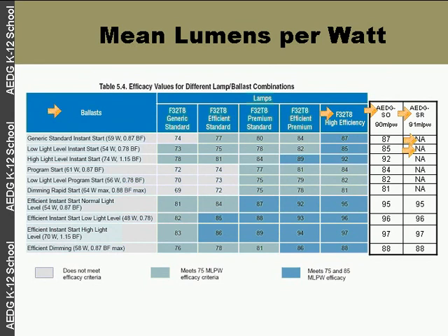We are seeing a requirement of somewhere between 5 to 7% of the floor area in skylights. So if you've got a 50,000 square foot warehouse building, you need 5% of that or 7% of that, somewhere in that range, in skylights in the ceiling to daylight the space. We want to see automatic daylighting controls on all those electric lighting systems in the daylit space. We want to see occupancy sensors on those same light fixtures so that when the space is unoccupied, the lights go off. And this is a very simple thing that you can do from the manufacturer.